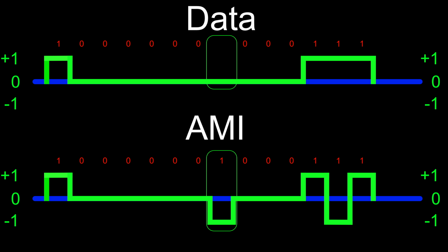The signal is then modified in some way to create a change that will represent a fixed state for a 1. The next 1 will result in that same change, but in the opposite direction. This was done because if you try to use the same polarity or direction of change, then the baseline can slowly creep upwards depending on many factors, and eventually it may raise to the point that the detection equipment can no longer tell the difference between a 1 and a 0.